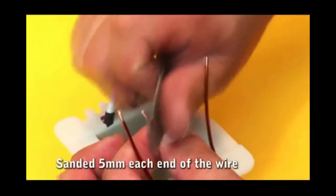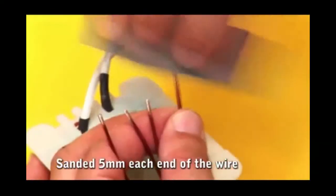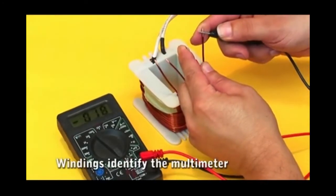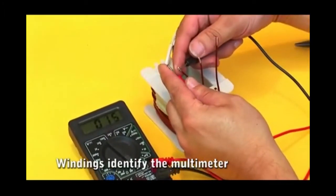We sand the ends of the wire to remove the dielectric insulating layer of varnish. Detecting the center tap of the transformer, the center point. We must identify the ends of the windings by measuring continuity with a multimeter.